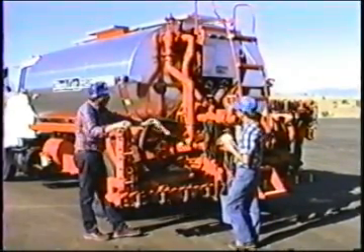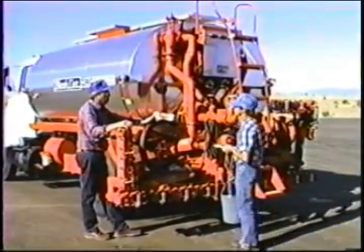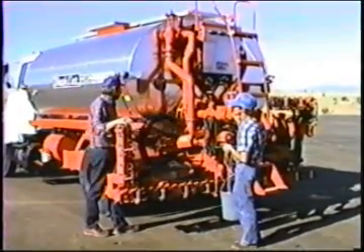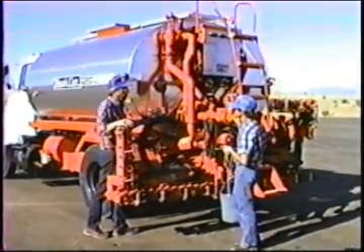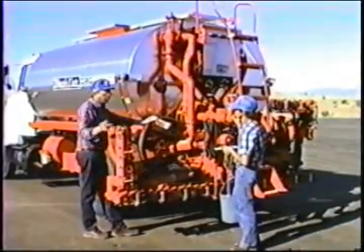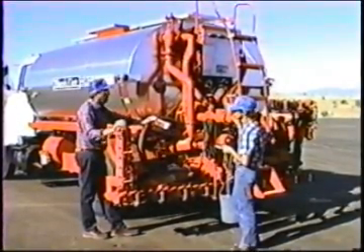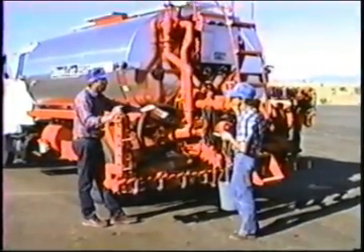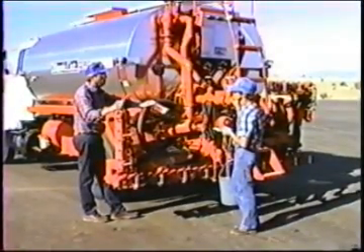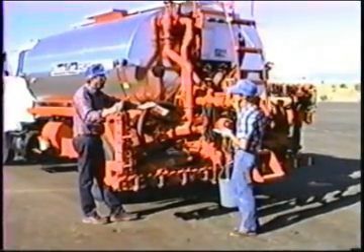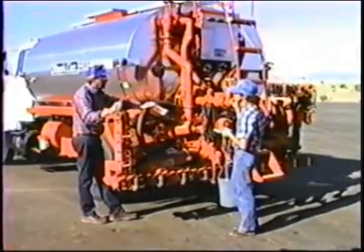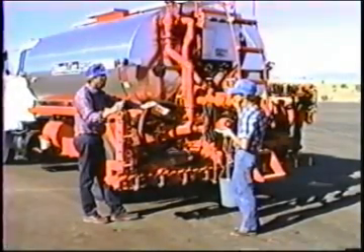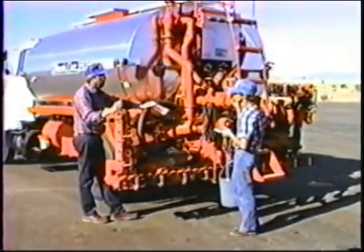The computer does everything that we've done with the slide rule. That is, it reads the travel speed of the truck off of the ring gear in the rear axle. It reads the spray bar width off of the switches on the control panel, whatever we have turned on. And it reads the desired spread rate from the window that we've filled in the computer. That is, we told the computer we want to spread 0.25 gallon per square yard. It sees those three numbers and calculates the fourth based on the first three. That is, desired spread rate, bar width, travel speed.